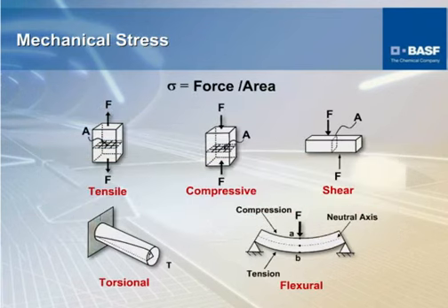Mechanical stress. Those of you that have a mechanical engineering background, this can all be basic in review, but it's still not bad to go over. Basically, any part that sees any stress, you should identify what the stress is. There's several different types of stress out there. First one being tensile. Good way to picture it is if you grab a steel bar and you just pull it in both directions, you're going to put a stress on that bar. Take that same bar and put it in compression, and basically instead of pulling the bar, you're pushing it together. That would be a compressive stress or a force on the bar.